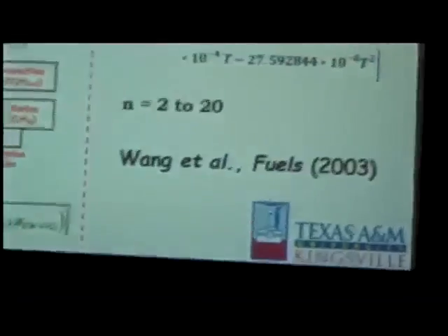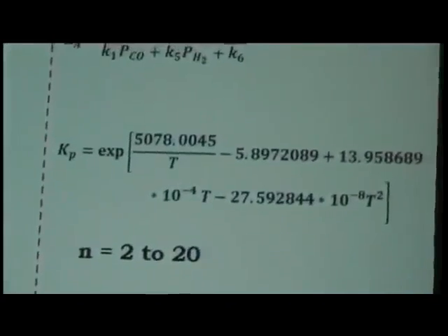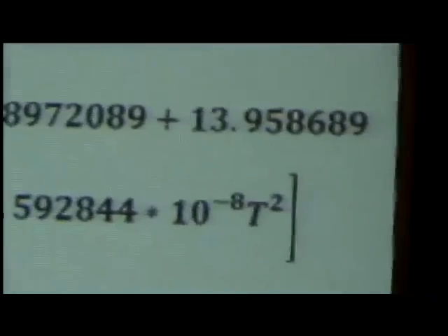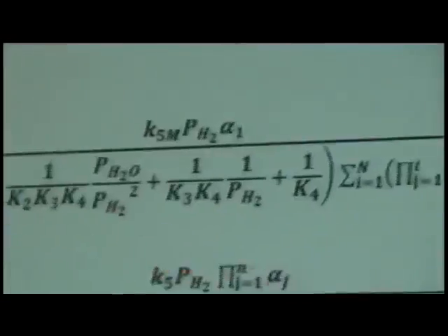Okay, so let's just take a look at an example of a reaction kinetic model. So we worked our way from the big problem of, say, business down to reactors. Now we're looking more on a local basis at reaction kinetic models. This example is a reaction kinetic model for Fischer-Tropsch synthesis, which is based on a fairly complicated multi-step microkinetic type of model. Here you can see what the rates of reaction are for the various species.